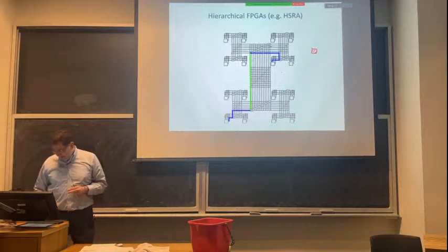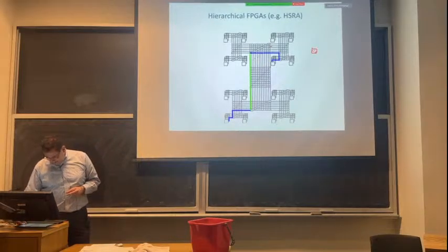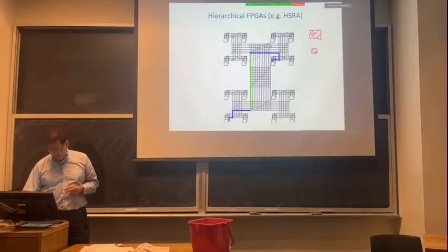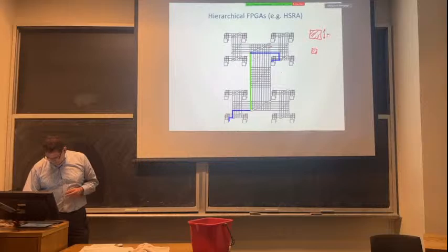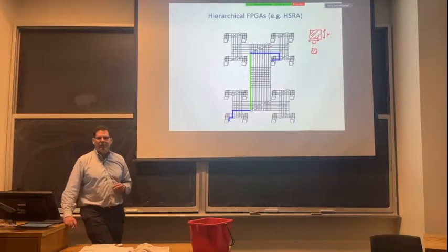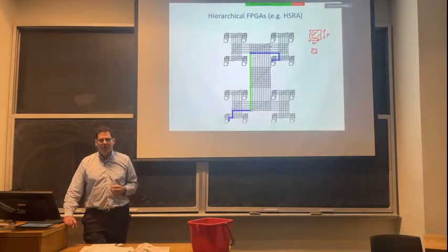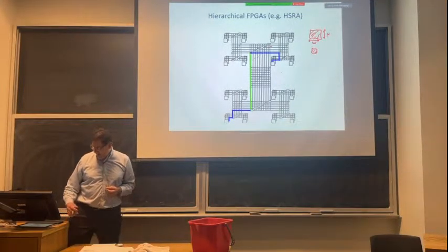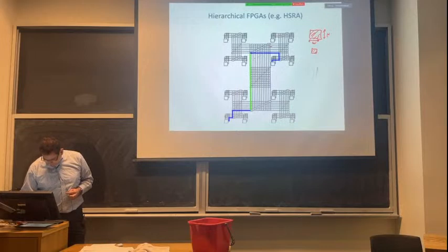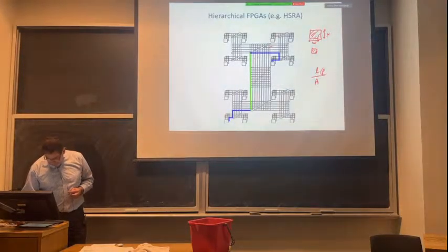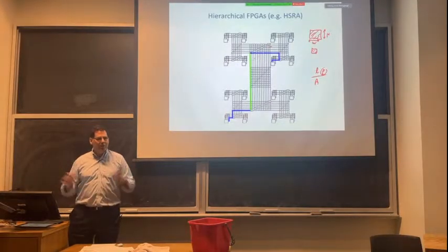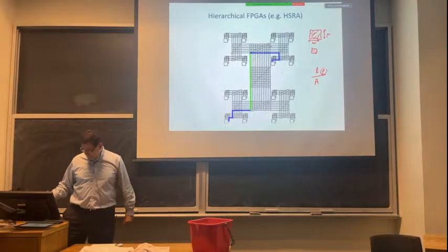And what's happening is as you scale a process, here I'll draw, here's an old process, say, big fat wires. This is the cross section. This is height, this is width. If you remember back to your first year engineering, you learned what the resistance of a wire was: it's length divided by area times resistivity. Resistivity we can't do much about. We're already using copper. Copper's a really good conductor.